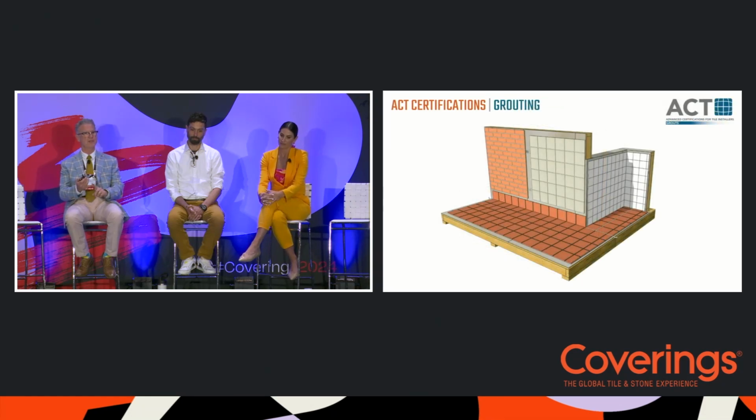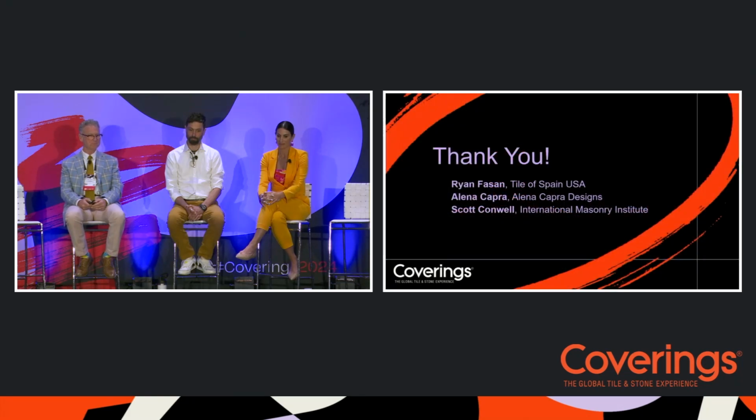And then finally, grouting is the certification for the finishing trade. So there are tile installers and then there are tile finishers. Typically it's the finishers that grout the tile, at least in commercial jobs. Is all grout the same? No. There's cement grout, there's now improved cement grout, there's sanded and unsanded, there's epoxy grout, there's urethane grout, there's single component grout. And each one of those different grouts requires a slightly different set of skills and a different set of knowledge. So this is where we certify our finishers.